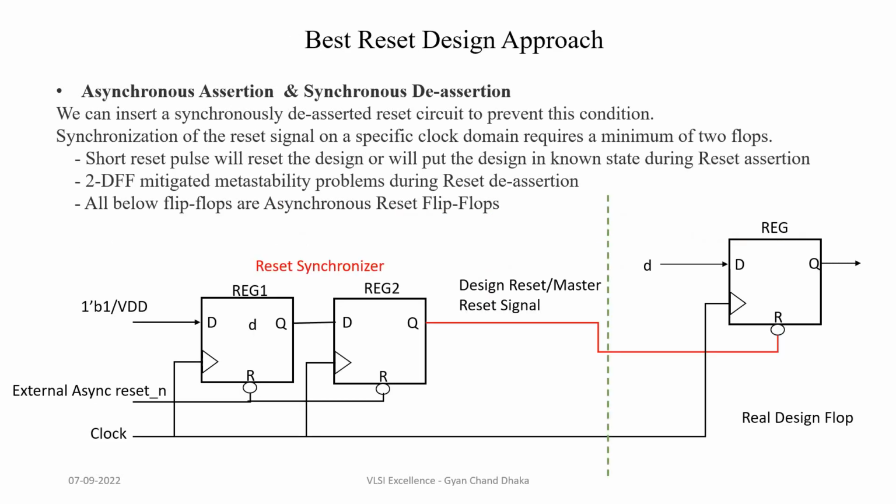Now let's see which is the best reset design approach. We saw the advantages and disadvantages of both reset design techniques, synchronous and asynchronous reset. In synchronous reset, the problem is that it always needs an active clock edge, and for most designs that is not acceptable, because most designs want to be in a known state even before the clock is running.